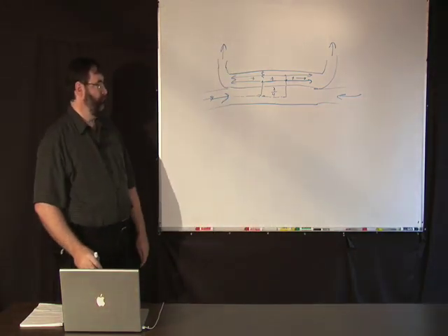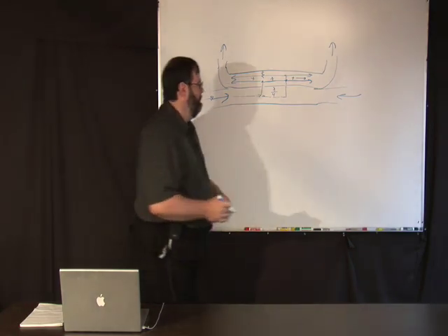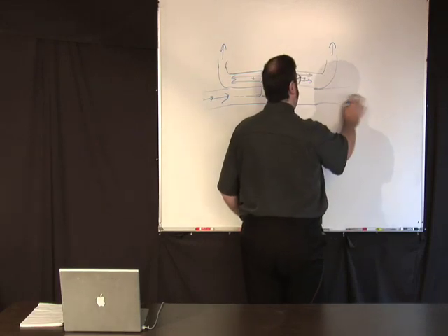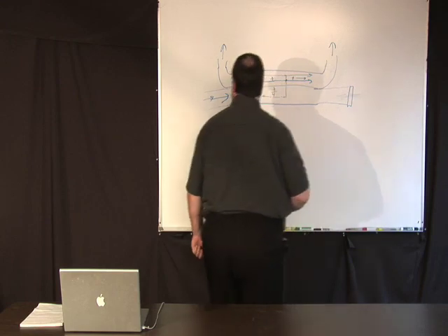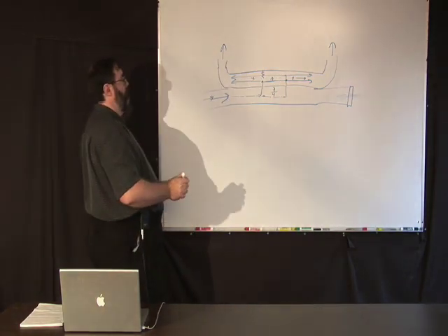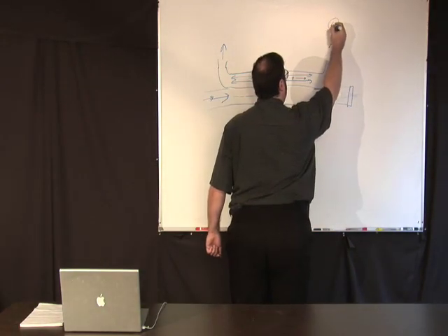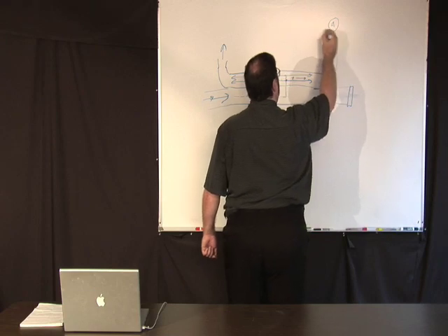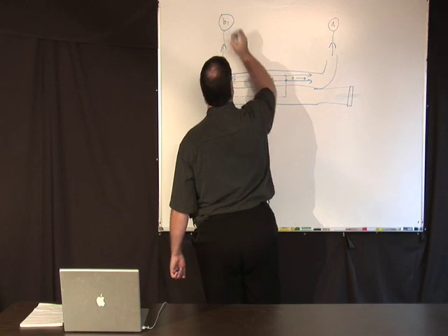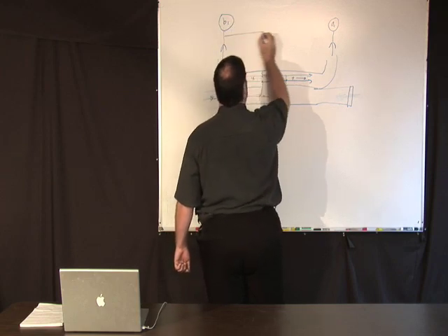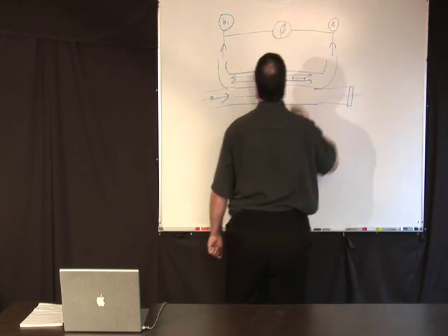Okay. So if you're going to build yourself a reflectometer, you're going to measure reflection. And let's say this is your test port out here. You have some waveguide flange out there. And let's say up here, you've got something to measure your amplitude, A1. And over here, you've got something to measure your amplitude, B1. And you have something that measures the phase shift, the phase between the two signals.